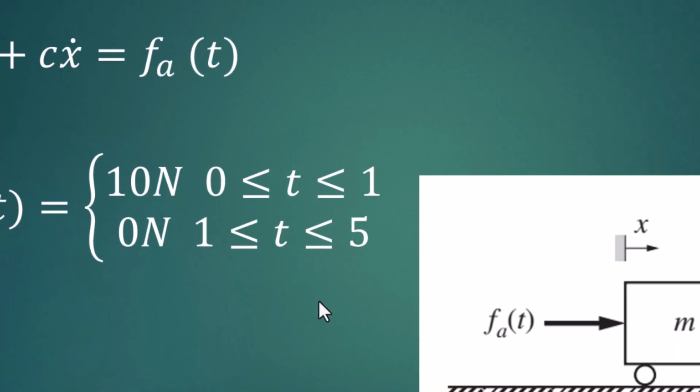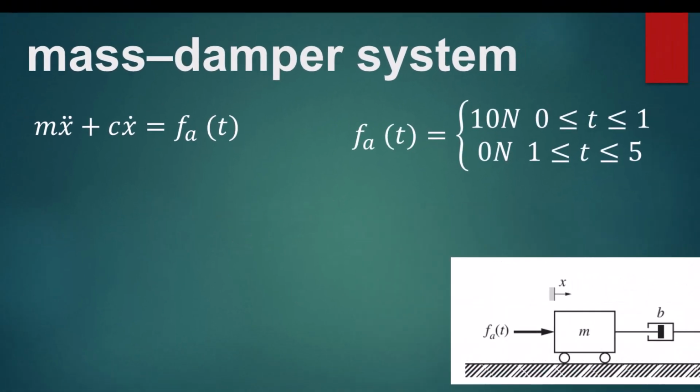So I take a moment to talk about how to convert this equation into a state space representation. You know, when you are using the ODE45 command and you want to solve a second degree differential equation, this second degree equation has to be decomposed into two first degree equations. So I define a variable named y, and it contains two state variables, x and x dot.